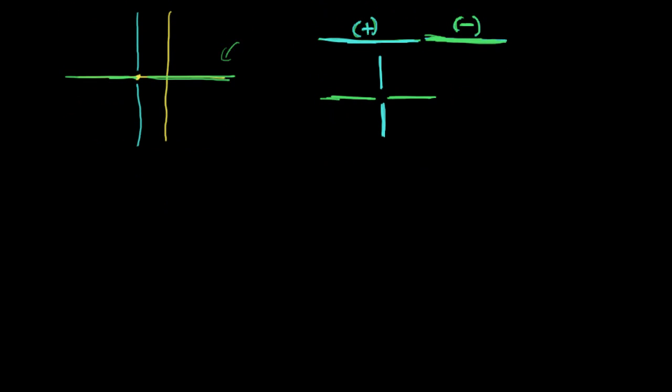If there are three more poles than zeros, or three more zeros than poles, the positive root locus asymptotes are distributed according to 120 degrees in this way, and the negative root locus asymptotes are distributed like this.